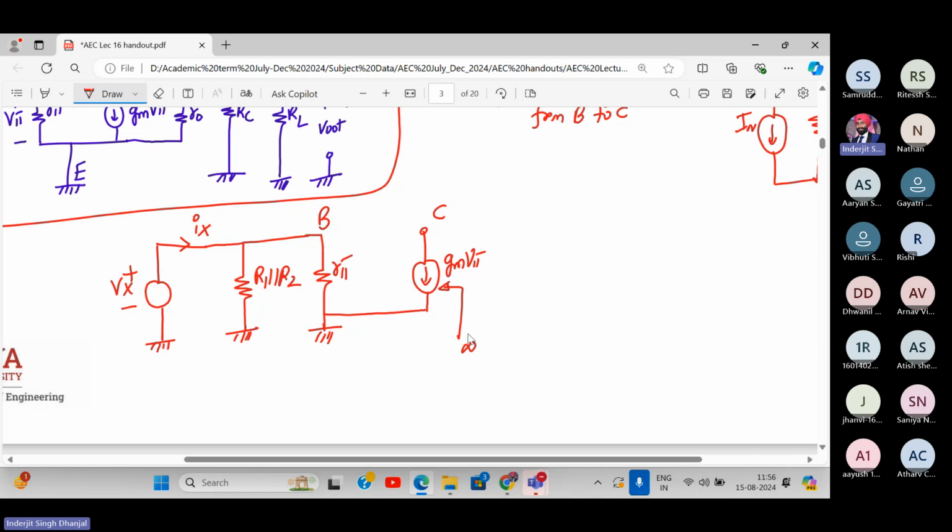All right, because there is no current now flowing between. See here, no current is flowing between base and collector, so they are disconnected, right? And we cannot analyze any current over here. Acha, will the base current flow into the collector now? Yes or no? Is there a connection over here? No, na, open circuit. So this will become redundant. There is no current flowing into the collector terminal. So therefore, this Ix, does it flow to collector current or base current? Base. Answer is simple. Yes, correct.